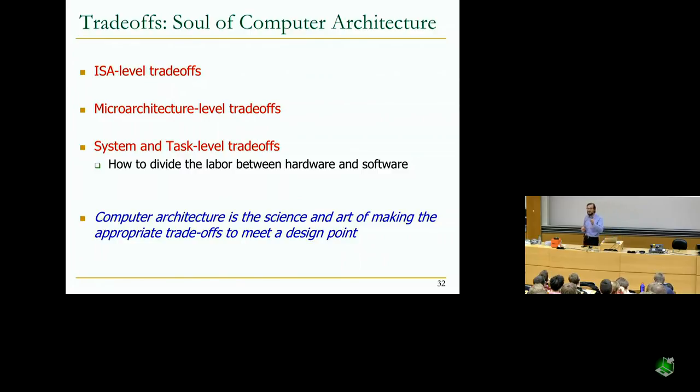The input to the instruction, the parameters, could be the pointer to the memory location that's the beginning of the array, a pointer to the memory location that's at the end of the array, and the size of the elements of the array. That's the interface, and the programmer expects the hardware to do quicksort. Right? That's certainly possible. That's an instruction. So the instruction can be complex or simple. That's a trade-off. And clearly the MIPS ISA designers, or LC3B ISA designers, said our instructions are going to be simple. But this clearly has an effect on a lot of things, which we're not going to talk about since we're already running relatively slow.